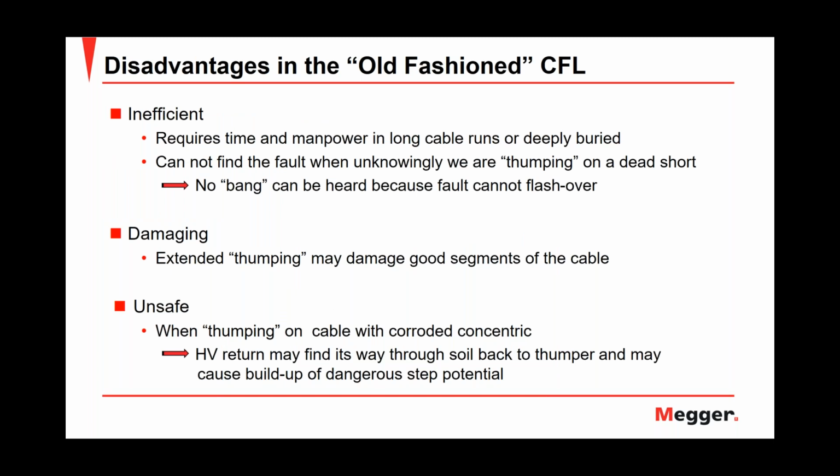It's inefficient because it requires time and manpower in long or deeply buried cable runs. For instance, let's consider that we have a 1-mile cable and the fault is 26 feet before the far end. If I have connected my surge wave generator or my jumper at the beginning, at the near end of the cable, that means that I will need to take a long walk to find the fault. For this reason, we said that it requires a lot of time.